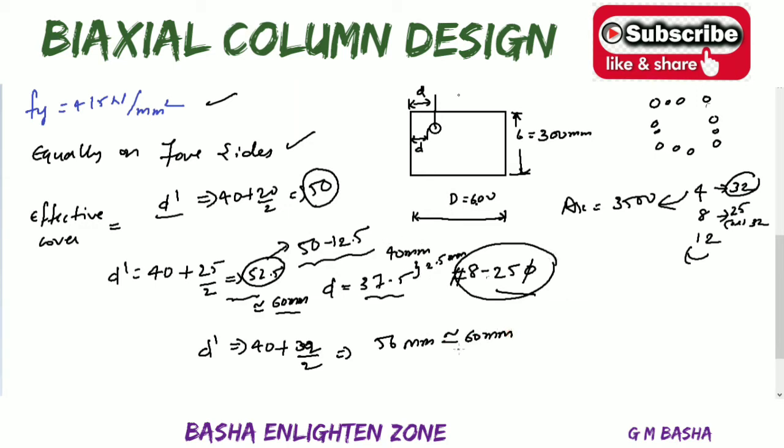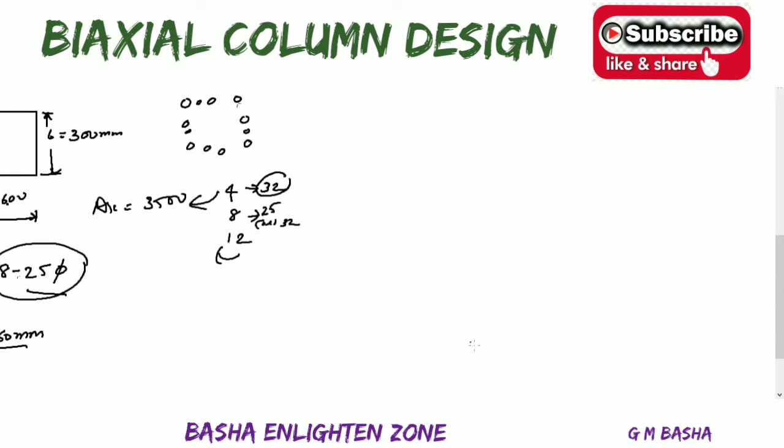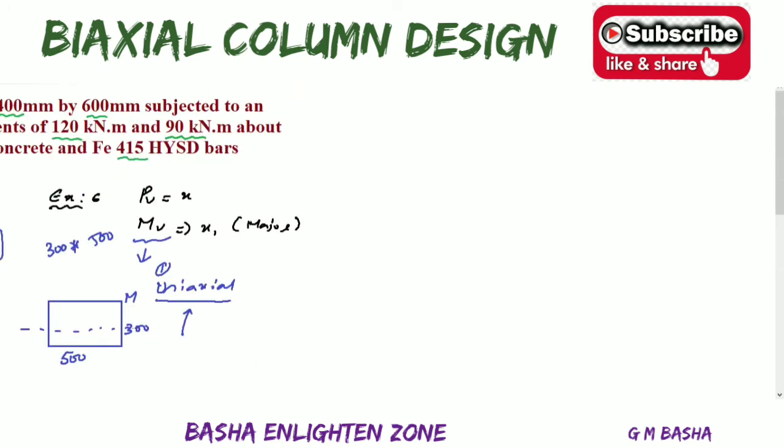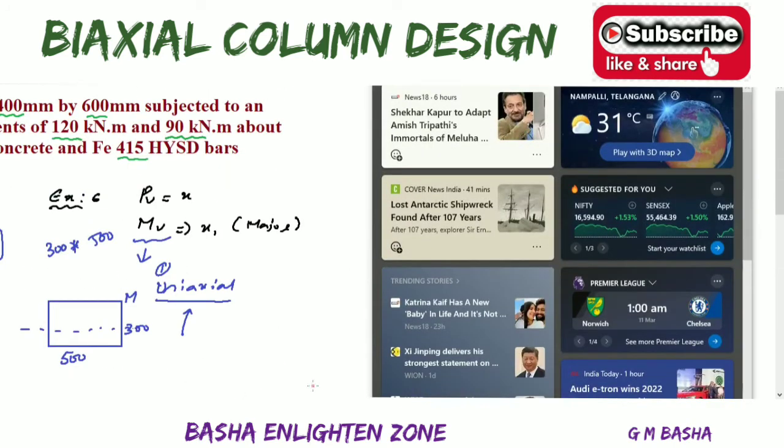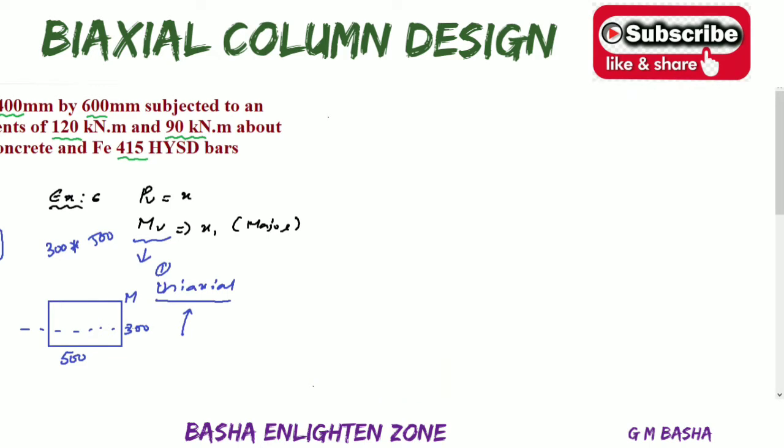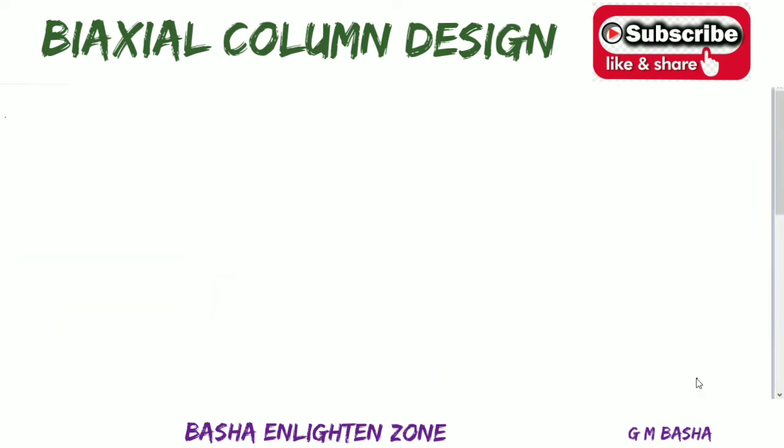If I am choosing this much of cover, maybe you can provide 32, 25 or 40, 20 bar, whatever, it will be suited. Okay, I think you can get a clear idea of what I explained up to now. Then move to the next step. After selection of this one, your d dash value will be equal to 60 mm.